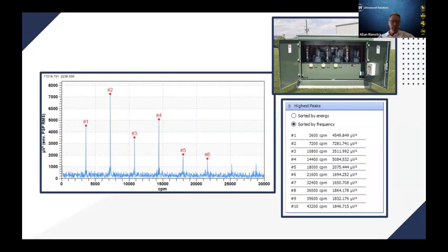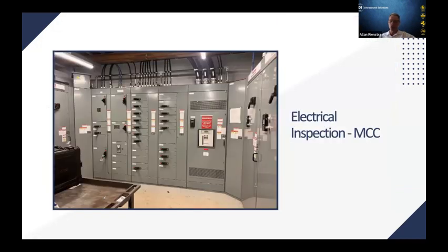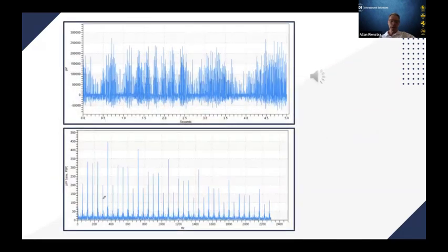We took that same signal and put it into our FFT, and again we saw 60 and 120 hertz peaks between each of these repetition frequencies. So we knew that it was corona. We knew it was part of the line frequency. Now here's an inspection that we did on a motor circuit control panel, and again outside. From just outside with the panel doors all closed, we were able to hear this problem right here.